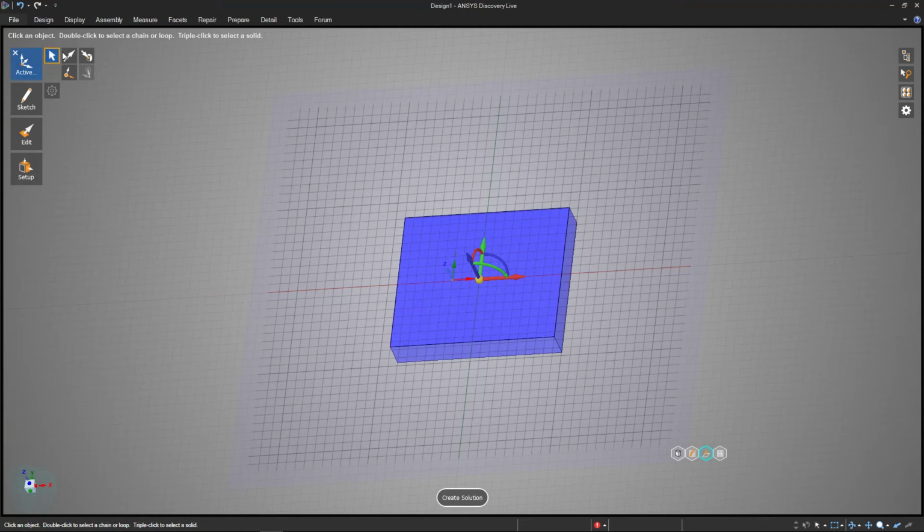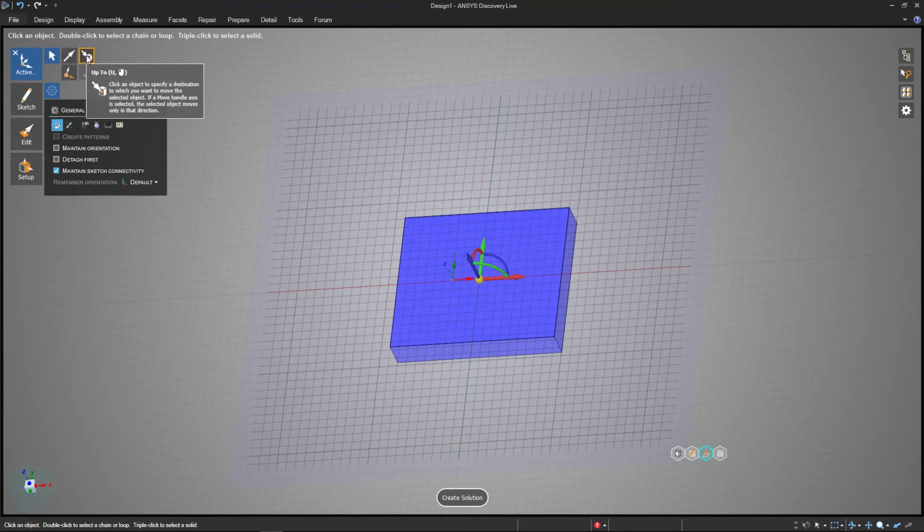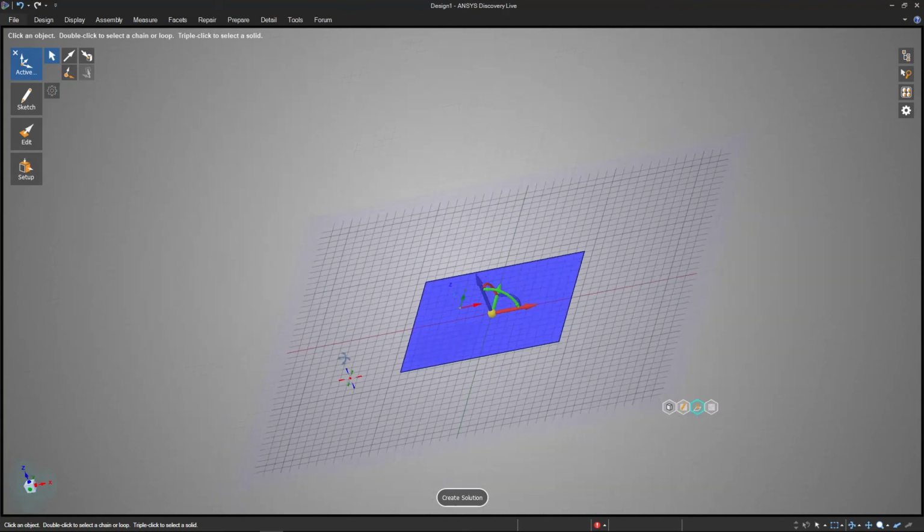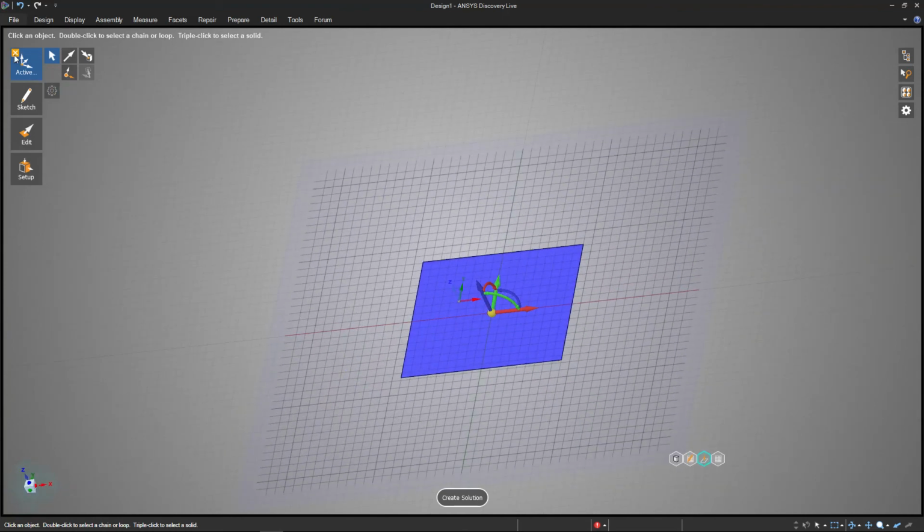So I'm going to use something up here. When you have the active tool, you'll get additional contextual options or even drop down additional options here, the most common ones being up here. Let's select this one, which is the up to option, and that'll allow us to move the sketch plane up to a face. I'm going to select the one that is the lowest. So we're all the way on the bottom of that cube that we had before. The shape I wanted to draw now is a rectangle. We'll put it right on the face here somewhere.